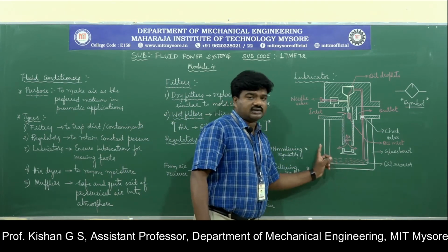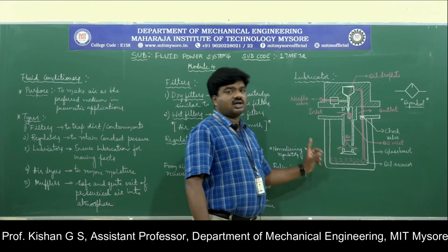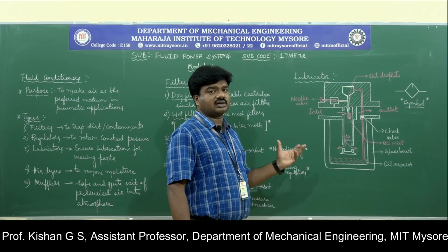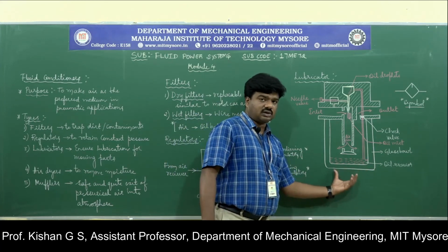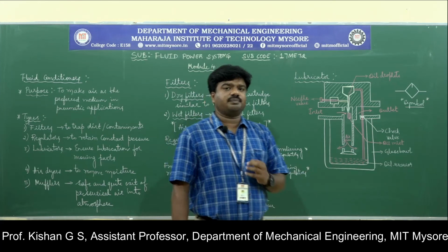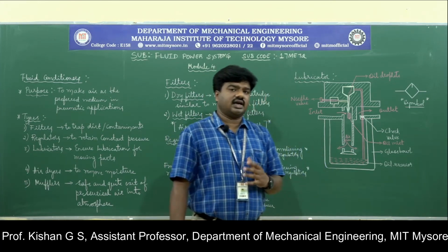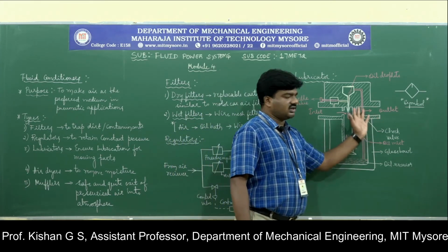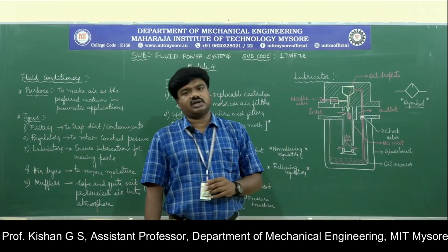and that will be subjected to swirling action. The swirling action results in the denser particles of oil accumulating at the bottom, and the lighter particles, or the air along with a fine presence of oil, will be taken out of the outlet and fed into the actuating medium.